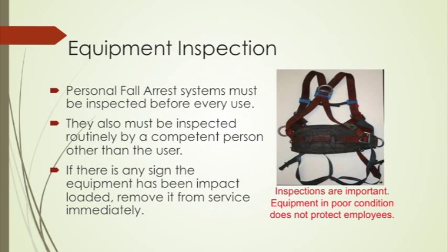Personal fall arrest systems must be inspected before every use and must be inspected routinely by a competent person other than the user. If there is any sign the equipment has been impact loaded, remove it from service immediately. Inspections are important. Equipment in poor condition does not protect employees.